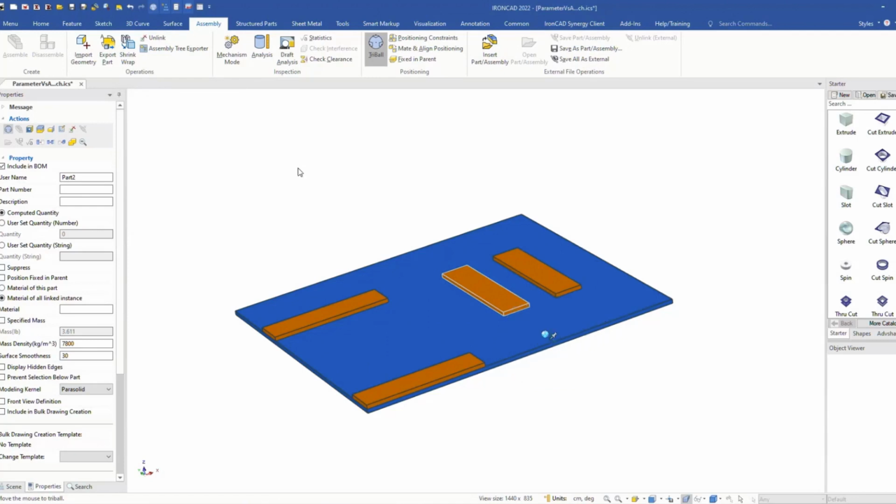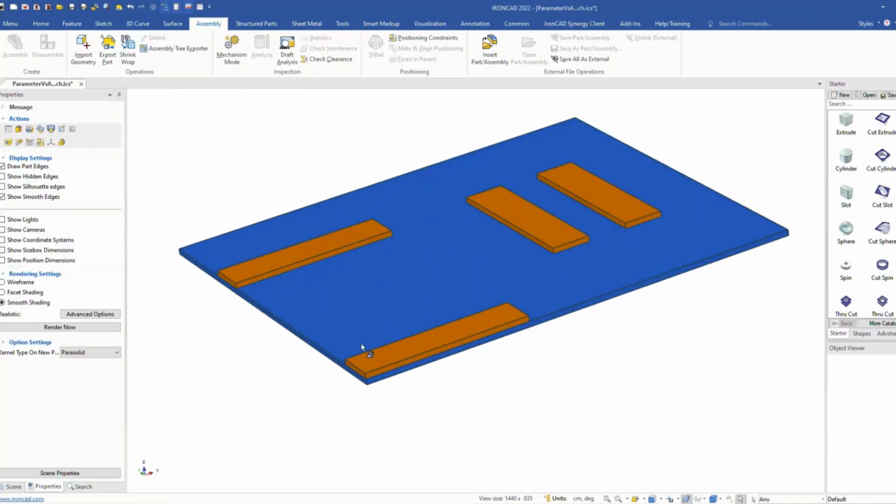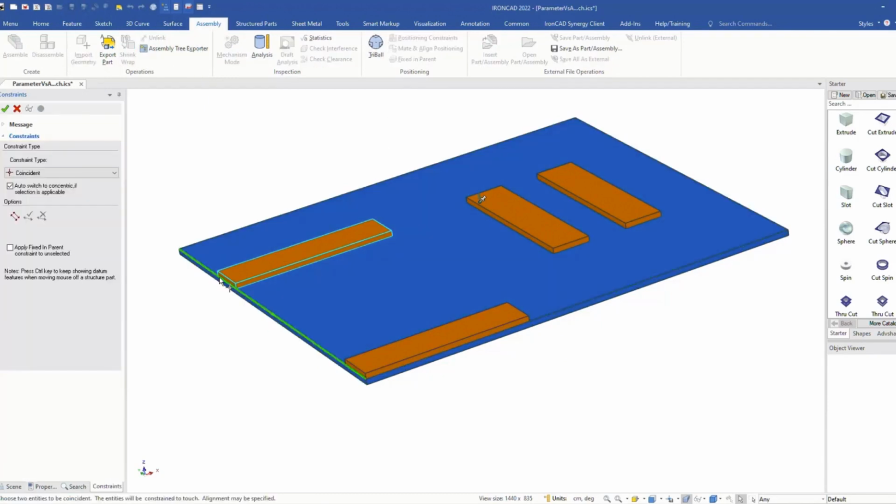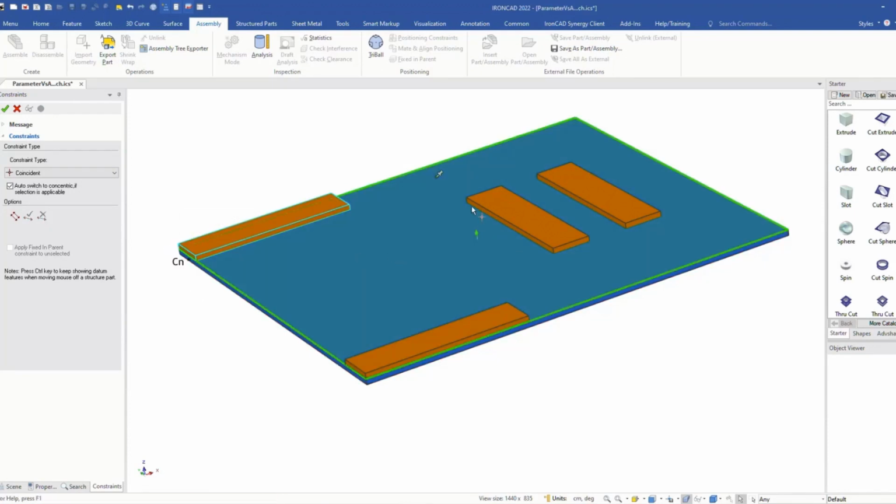Okay, so now we've got all of our pieces that need to be on these corners, and we need to basically do that same thing. So on this part here, we'll do that same position constraint. We'll move that to that corner, and if you hit the left key, that'll actually apply that, and we can kind of repeat this around. So in this case, we need to move this one to this location here, hit the key to lock that in place. And now our issue is, how do we get the other one in place?